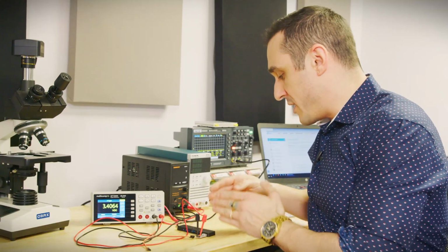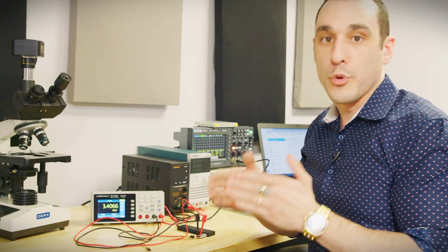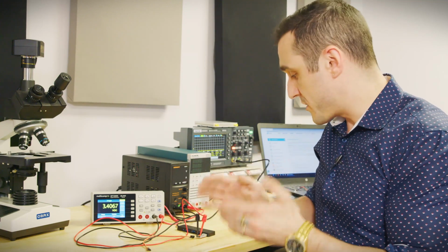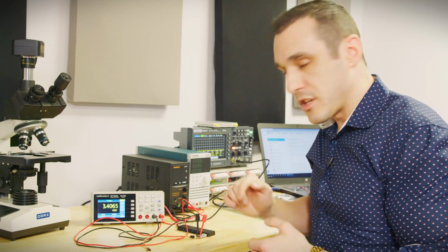In order to do that, we need to lengthen this module out a little bit to make room for some TVS diodes. We'll place those TVS diodes on this particular custom board that we're going to build, then we'll be done. So let's hop into Altium Designer and get started.